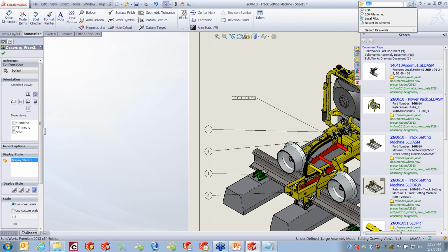Now, why this is a little bit different in the way that the names are is a little bit confusing, but if I go under here and say search keywords, and let's say I want to find one of the ones that I filled out that was titled test. Well, that was listed under stock size, and stock size isn't listed here by default. Well, I can pick any of these, but notice the formatting of what I have up here. It puts the property, then a colon, and then you type in what it is you're searching for.